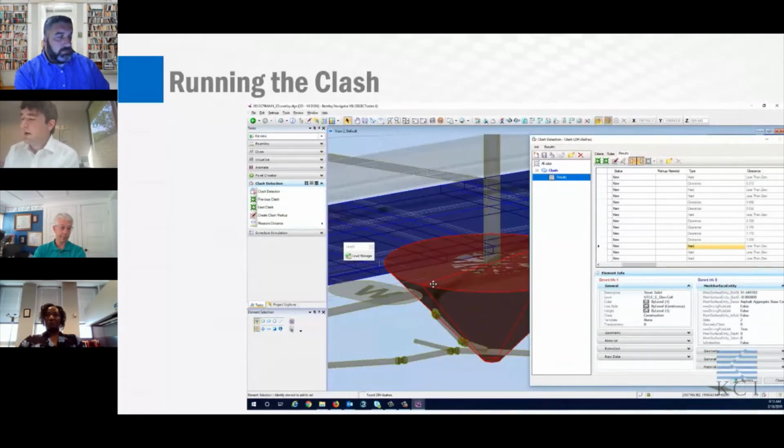When you are looking through the clashes that are generated, one thing to keep in mind is that if you have an item, let's say it's a telephone line that is now above ground that's supposed to be buried after a proposed cut is taken from, let's say, station 10+00 to 20+00, the clash will highlight this conflict at multiple locations along this range of stations. So you have to weed out some of the multiple clashes, as we want to say that this telephone line is in conflict from station 10+00 to 20+00 instead of continually calling it out in whatever intervals you set.